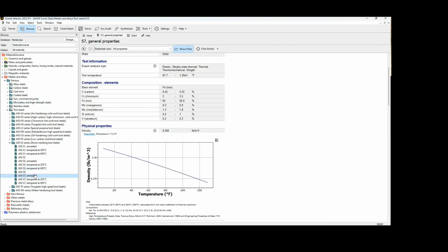Could you then use that data? Yes, you can take it out of this, bring it to your SolidWorks, bring it to your Ansys, and then change it there. Because as I said, here we provide a range, and when you export it, it gives you the mean value. Sometimes you want to be conservative for your modulus of elasticity, so you choose the mean value, and then you can go ahead and change it in your Ansys or SolidWorks.